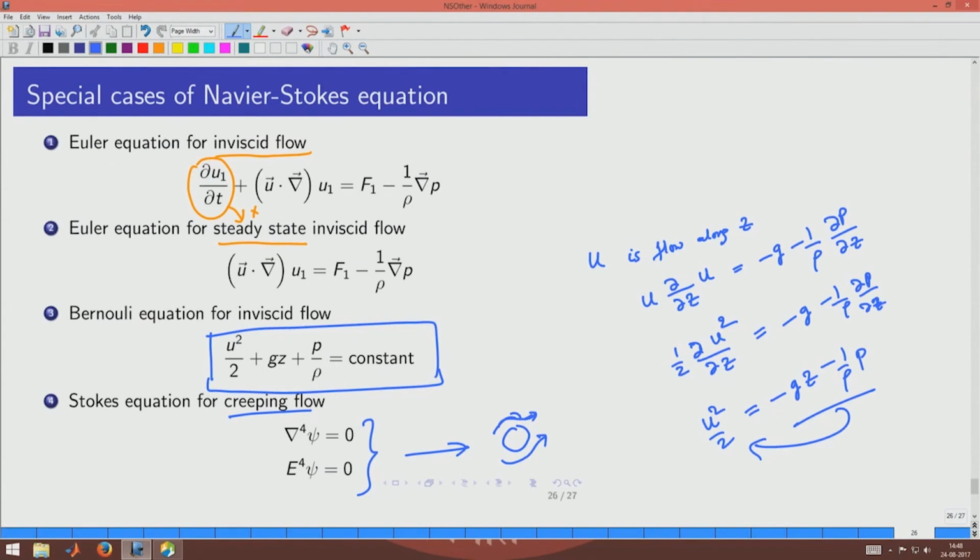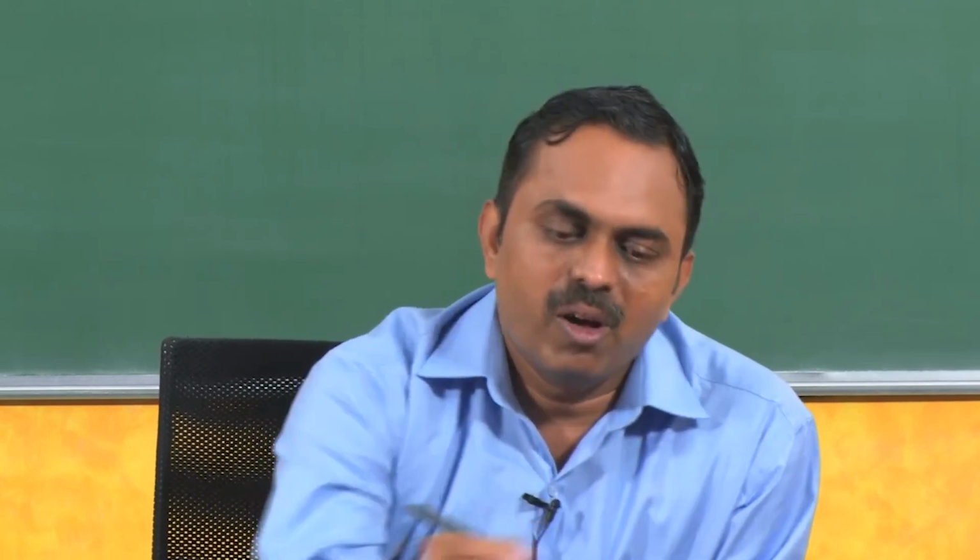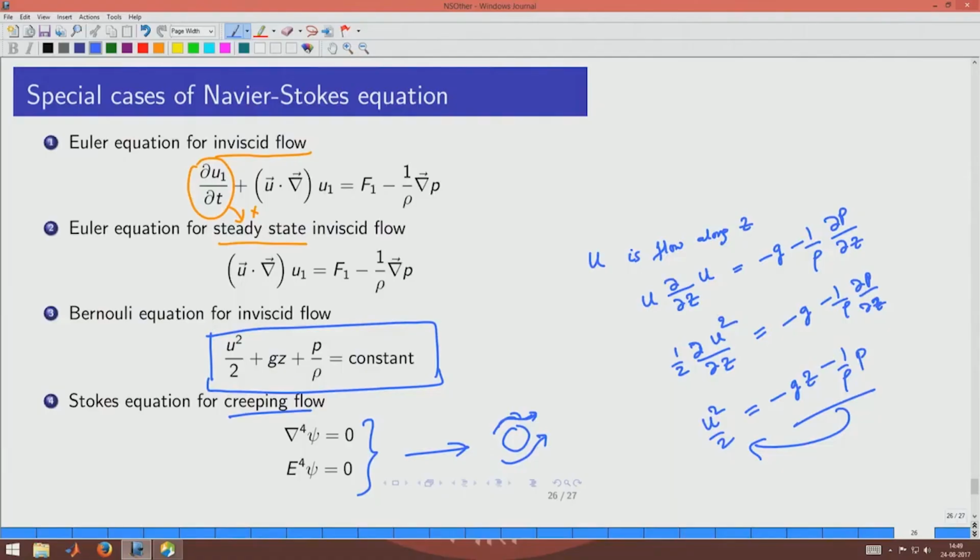We could see that all these equations are basically special cases of the Navier Stokes equation. So, it is a very good idea to see how the Navier Stokes equation has been derived and how different terms are dropped when some assumptions are made to arrive at these equations. That would be a far more generalizing approach than having to derive each of these equations separately and still not knowing how all of them can be generalized. We must always remember that the Navier Stokes equation is the most general form that encompasses the physics covered by all these equations that I have listed here.